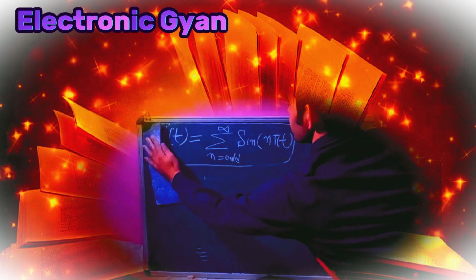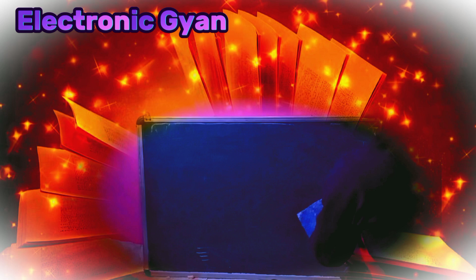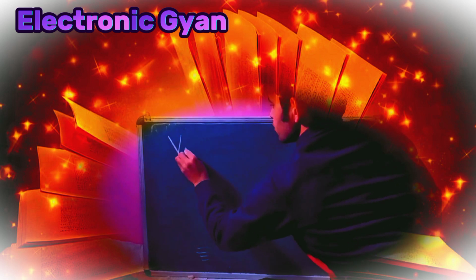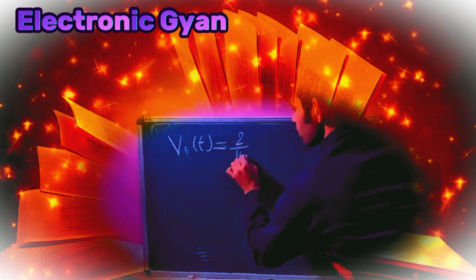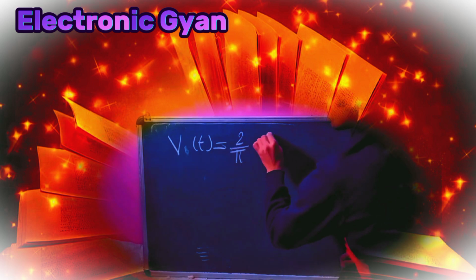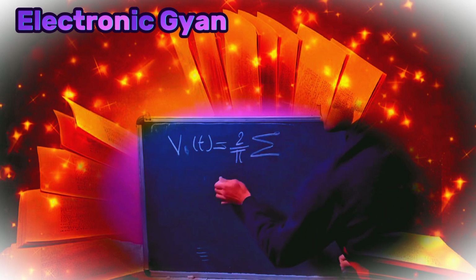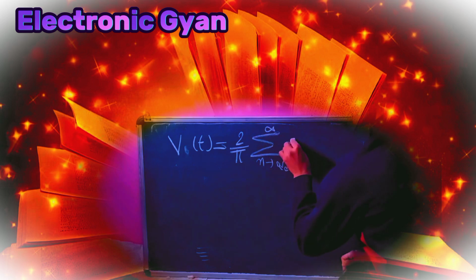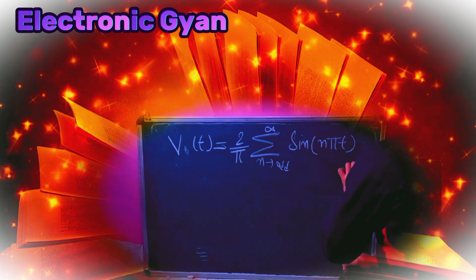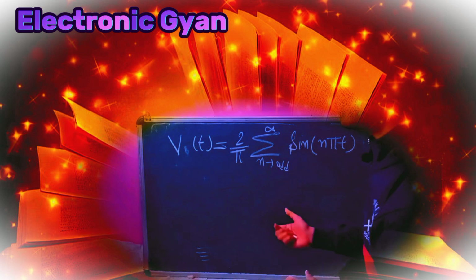This is the input that we know very well. This is my v(t), and here 2 by pi was there, I just didn't mention it earlier, so please note it down. So v(t) is 2 by pi, summation over n odd to infinity, of sin(n pi t) divided by n. This is what we have applied to the RC low pass filter.